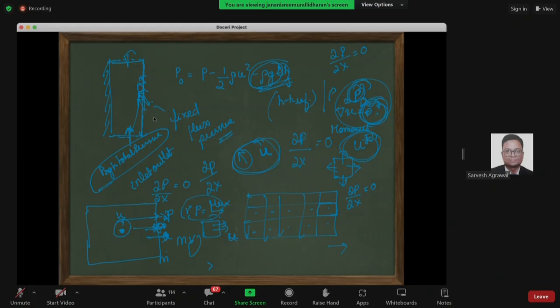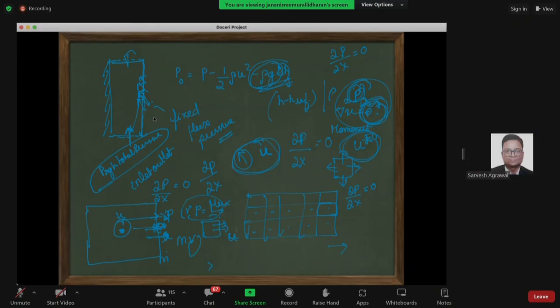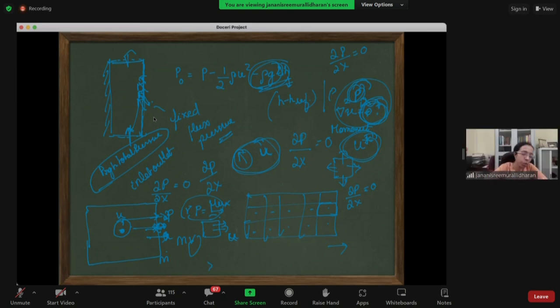Yeah. Is there any possibility that if we are doing simulation for natural convection in 2D domain for PCM, phase change material, and 3D domain for the same geometry, is there any possibility that we get different phenomena of natural convection for 2D and 3D for liquid fraction? Absolutely. Yeah. Your 2D, even for your forced convection, your 2D and 3D will be different.